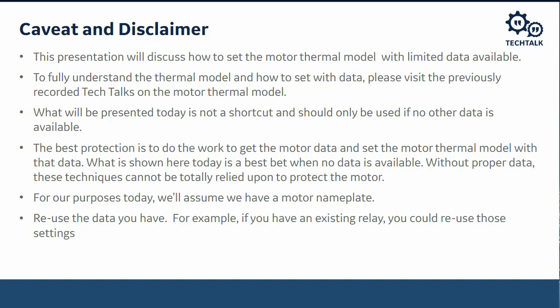Now, one of the other things that I should say is if you've got an existing motor, you should make every attempt to reuse the protective data that you have on that motor. So if you've got an older electromechanical relay or electrothermal relay, that relay will have settings around the pickup.